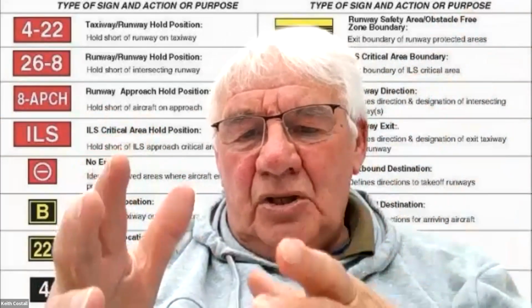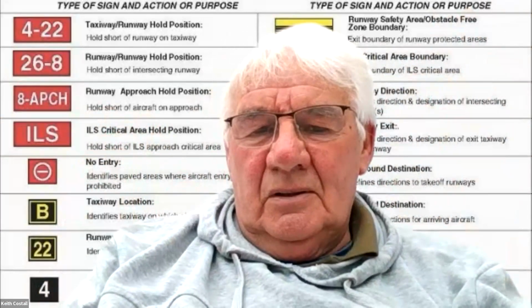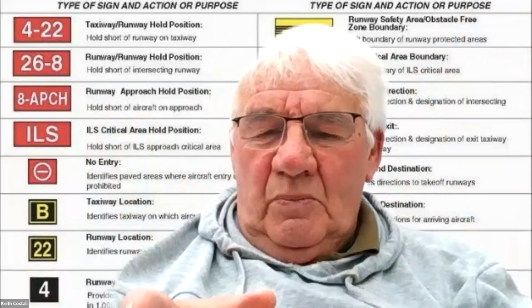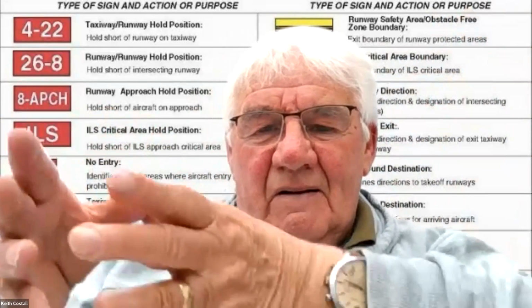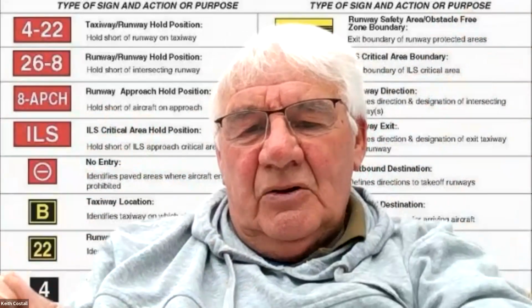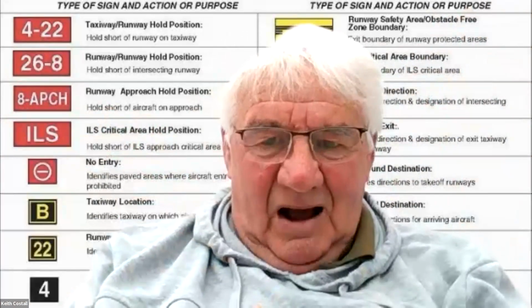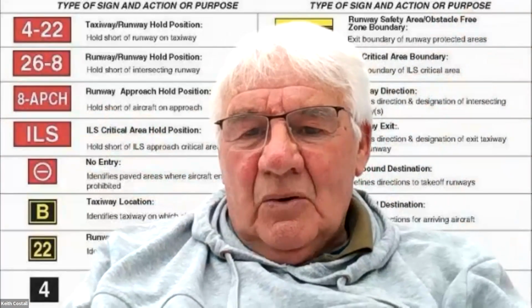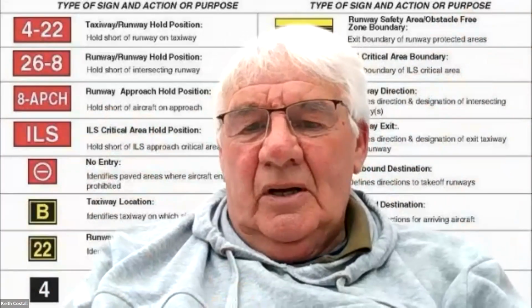But when it comes to a new installation, we would be expecting insulation resistance values at a dramatically higher value than that when everything is new.